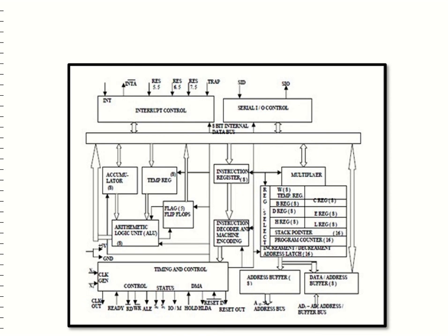Serial input-output control. It controls the serial data connection by using these two instructions, namely serial input data and serial output data. Address and data bus. Data bus carries the data to be stored. It is bidirectional, whereas address bus carries the location to where it should be stored, and it is unidirectional. It is used to transfer the data and address to input-output devices.